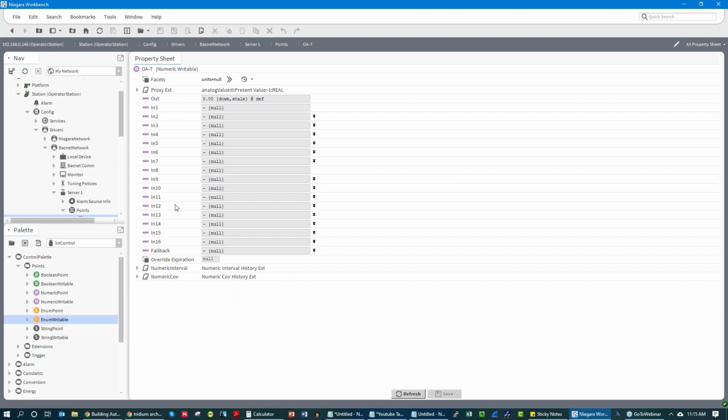And so that's what our field controllers are doing. They're taking logical or physical points, in the case of outdoor air dampers, outdoor air temps, return air temps, etc., and they're converting them to software that can then be brought up into our supervisory device and represented as graphics.